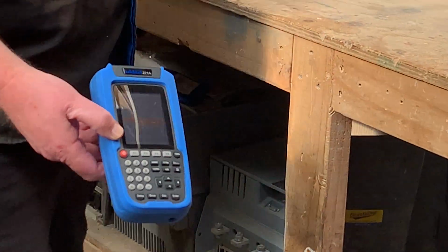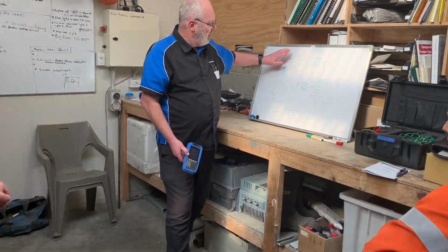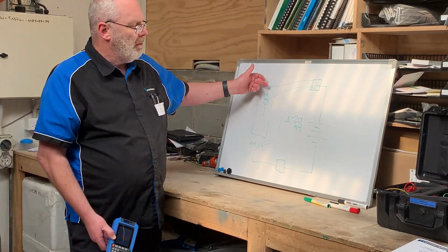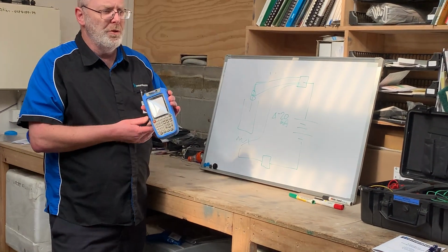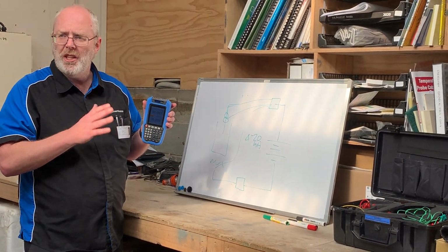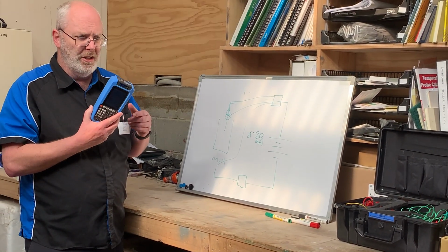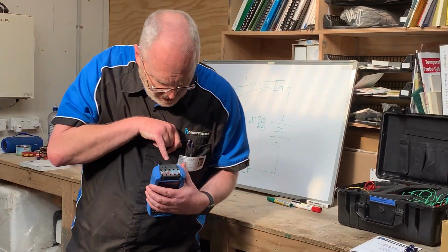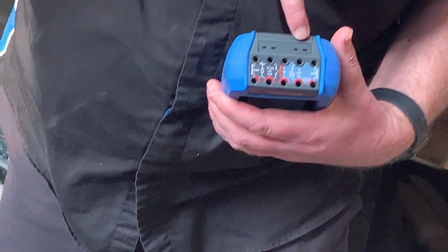So in this case, we might say, well look, why don't we simulate a calibrated thermocouple, so we'll say there's no transmitter in this case. Let's simulate a thermocouple at 300 degrees Celsius. So let's produce a calibrated type K thermocouple signal as if it's 300 degrees. And it's completely calibrated. You put your hand on a stack of Bibles and know the output is right. So on the top of the instrument, you have 2 thermocouple sockets. One says measure, one says source.